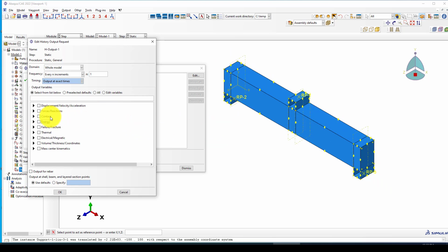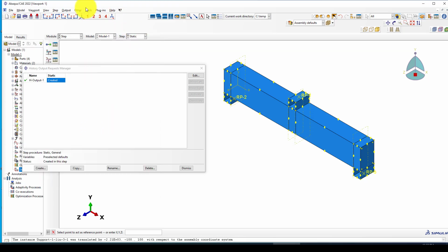We should create at least two nodes, but before this I should create some set here. Let's create a set. In this set I want to measure this deformation in X, because I want to apply a roller. So when we push the load here, it will deform.